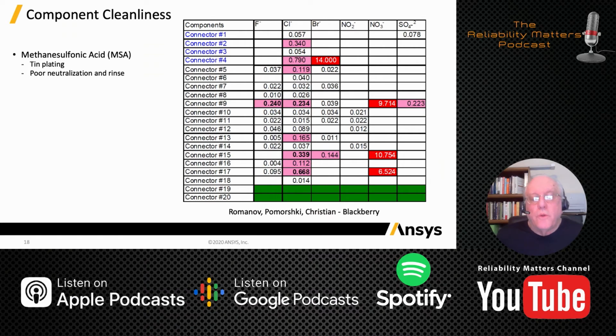So you're left with a gloopy, goopy flux residue mess that has not been fully processed. So the current state of thinking there is let's not talk about this in terms of activation. Let's talk about it in terms of passivation.